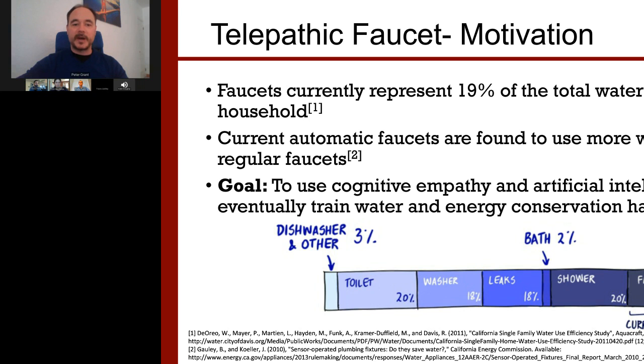For instance, I talked about the standard distribution loss multiplier and how that is a way to estimate the amount of hot water that's trapped in pipes. That was based on data in Californian houses. Maybe you have algorithms that are more accurate for your location and the types of construction in that city, so we could consider changing that. Maybe you have a different algorithm for mains water temperature that you would want to use. So we could consider that.